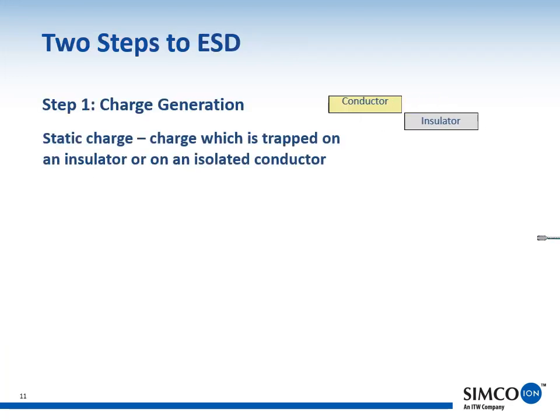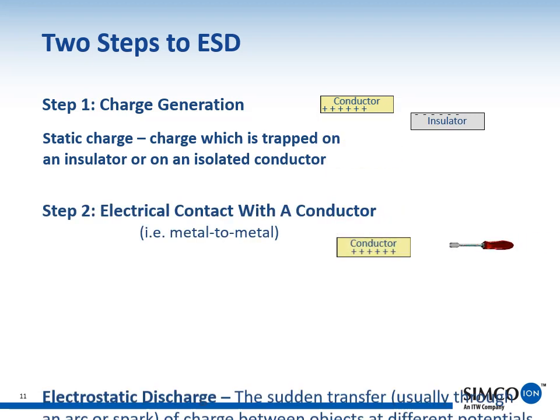There are always two steps leading to an electrostatic discharge. First, you must charge a conductive item, such as an integrated circuit. The conductive item, in this case, is triboelectrically charged by an insulator. Then the item makes contact with another item that is at a different potential.